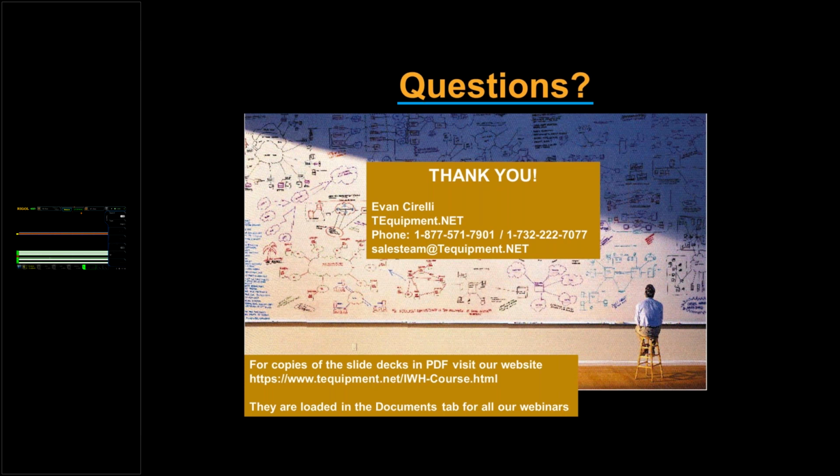So the other nice toolkit is really the ability to use the search and mark table. So instead of RF pulses, once you're dug in on the embedded side, you can go ahead and look for runts or pulses, and you can search for multiple triggers within a capture and get sequences and timing of events in a more challenging way. So I think that's really the set of analysis capabilities on the oscilloscopes.